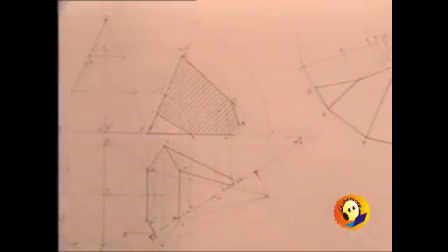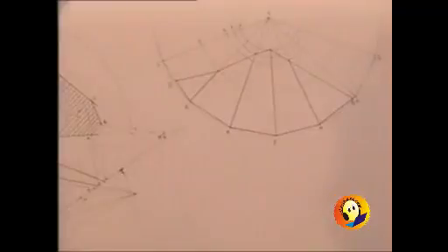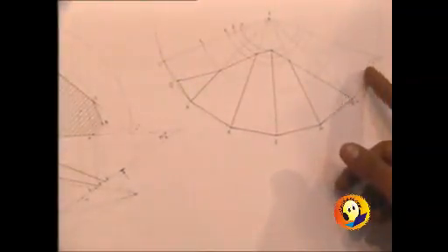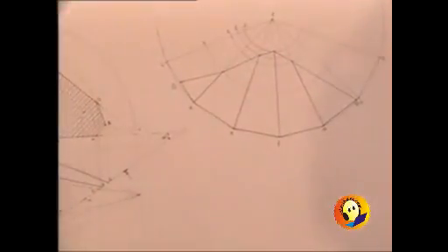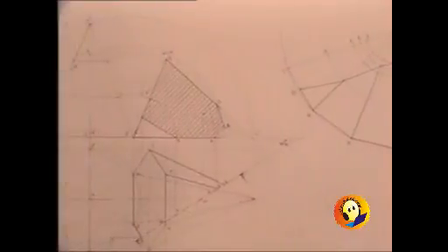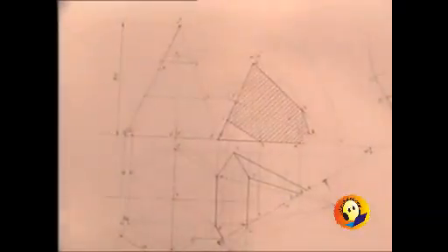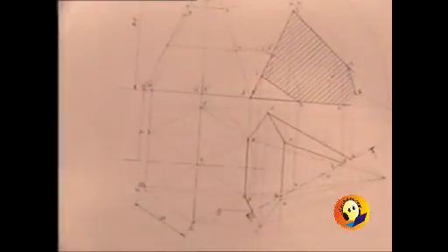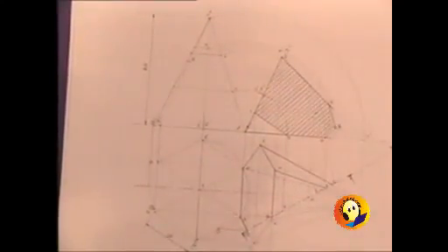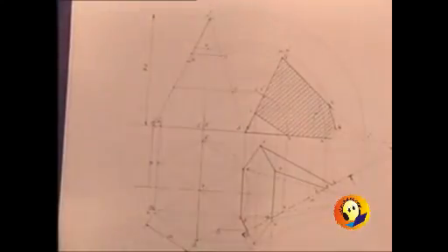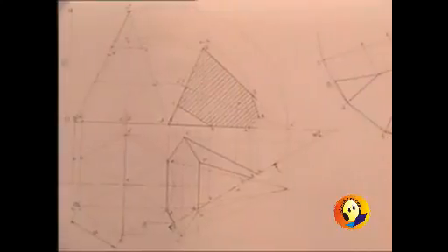And then the development, and I had purposely chosen the points so that the development will appear in a continuous manner. Points on the generators of the pyramid can be marked directly by using the arc technique, whereas if the point would have been on the surface, I should have used some other method, that is drawing the lines parallel to the base of each triangle. Aiming will always help us to complete the problem correctly.